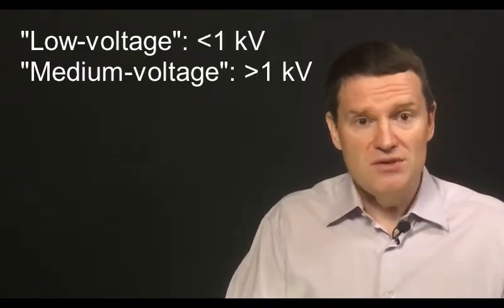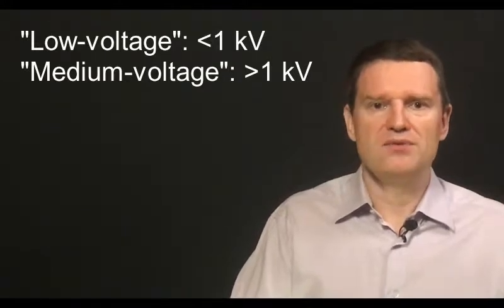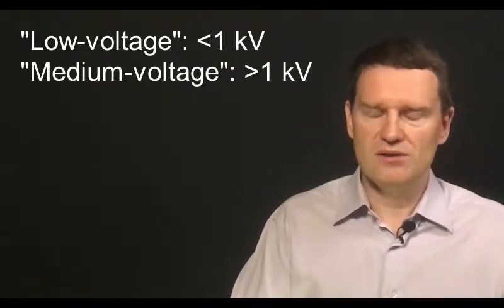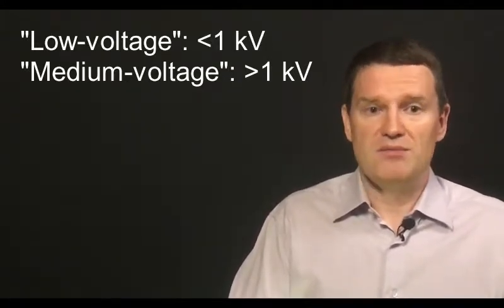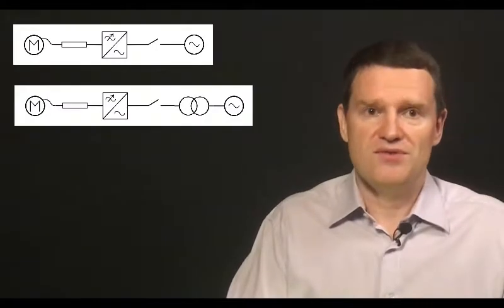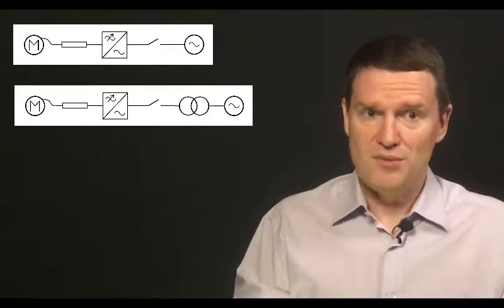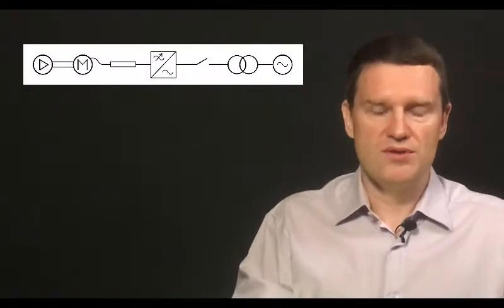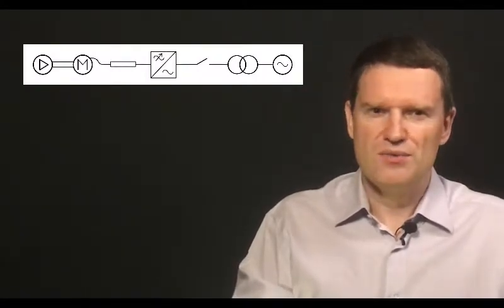Well, we know that medium voltage topologies always include some sort of a transformer, while low voltage drivetrains can be built both with and without transformers. So, since we have to analyze motors with 3.3 and 6 kV voltage level, we will have to use topology with a transformer. What else do we know?